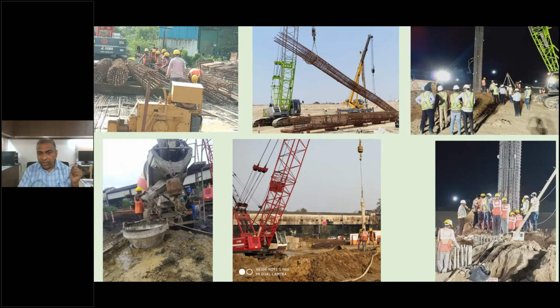Then you can see here, once the cage has been inserted, the tremie pipe is lowered. After lowering of the tremie pipe, concrete is poured through the tremie pipe in a measured quantity, and thus the pile is cast. But in between there are many operations.